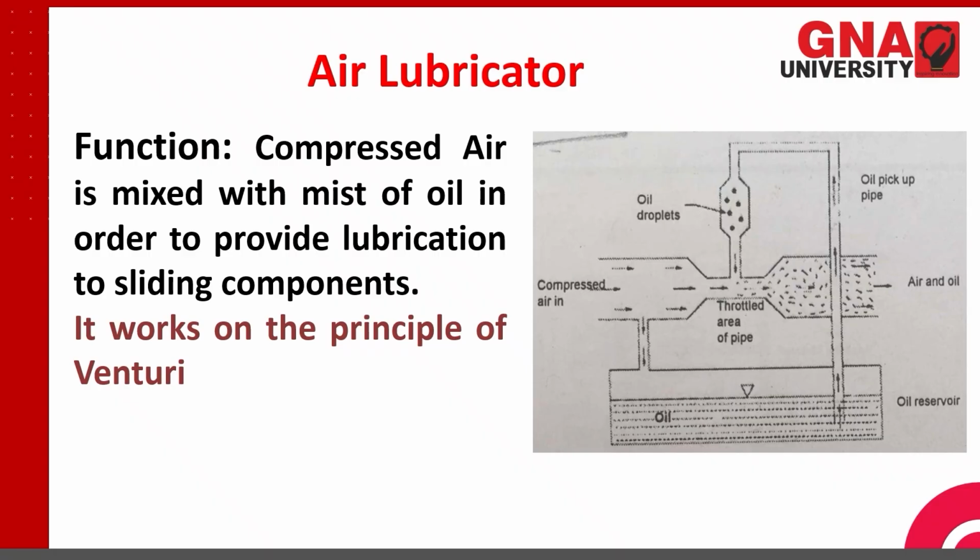So when I have set a limit over here by rotating this screw, the fluid pressure is acting upwards and the spring force is acting downwards. When these two forces become equal, and the supply pressure rises a little bit above the spring force, the diaphragm will lift up and it will allow the passage of the air to the other side.